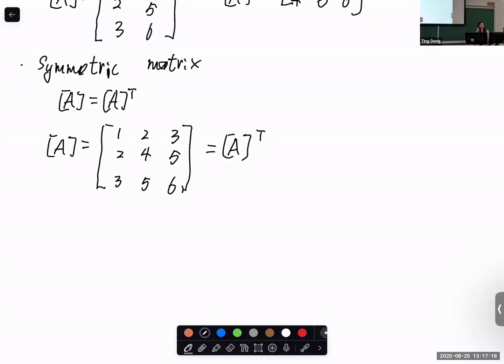Principal stresses, remember? Let's say you have a structure with torsion, tension, compression, bending, and transverse shear, and you use all of those to calculate the 3 by 3 stress components. You have sigma x, sigma y, sigma zz, tau xy, and all the shear stress components and normal stress components. Now let's say I want to decide if the structure will fail or not. If our material is brittle and we compare with the maximum normal stress of the material strength, what do we need to find out?